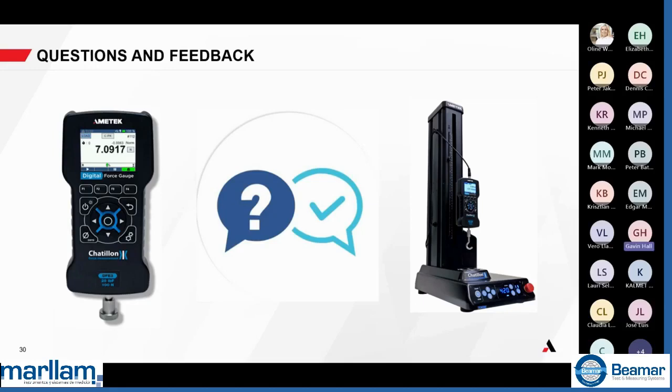Sending commands to the test stand is something that's being developed, so we can send serial commands to the gauge and potentially the test stand going forward. This makes it more ideal for PLC environments where you want an external computer control or overriding control to use the gauge as a piece part within a test procedure. So yes, there is an ASCII command set that can be sent to put the gauge in a certain mode, to change units, to retrieve particular data, and to start and stop the test.